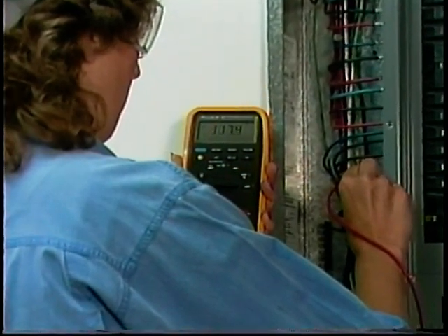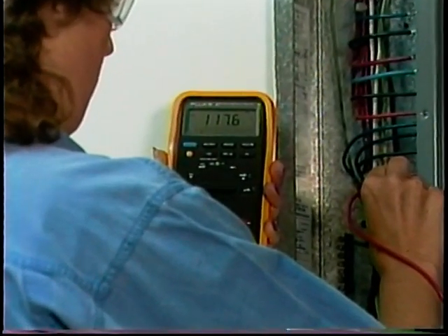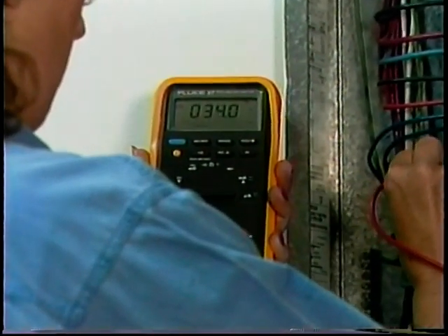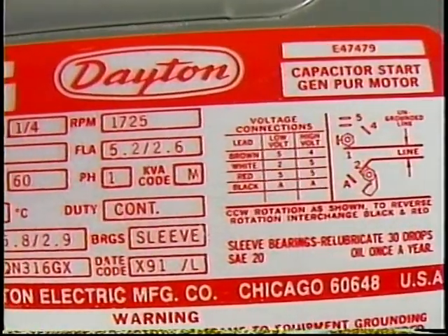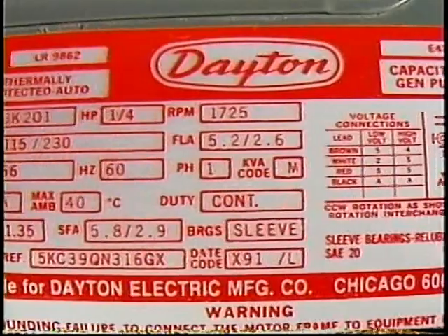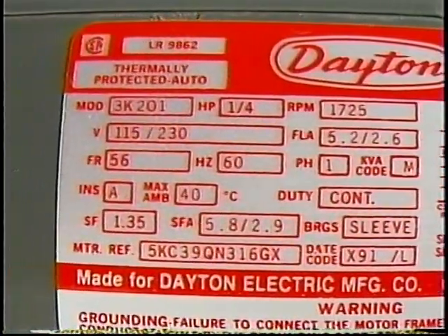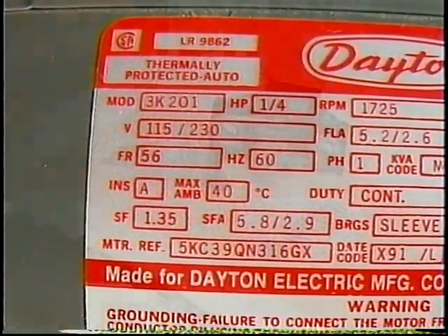Like Ohm's law, the power formula is used to predict what will happen in a circuit before power is applied and when troubleshooting. As long as two of the three electrical values, power, voltage, or current, are known or measured, the third value can be found.